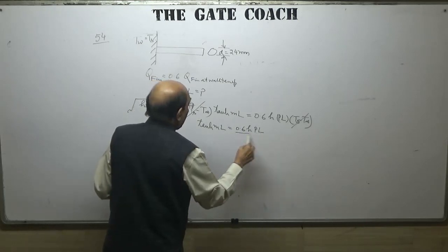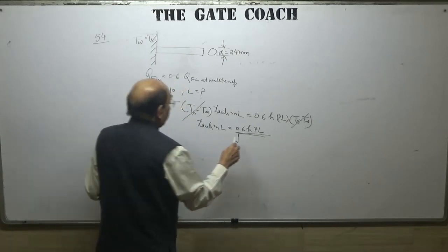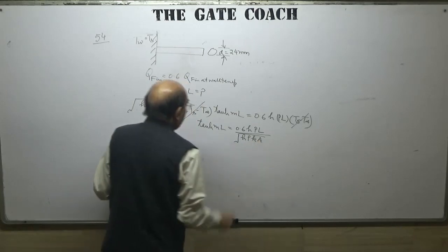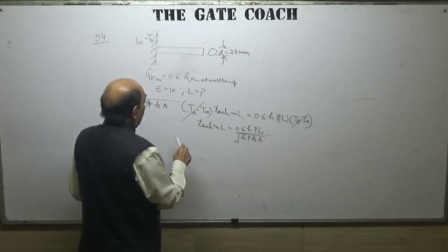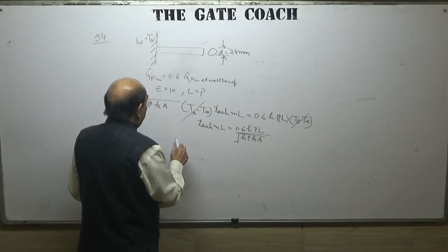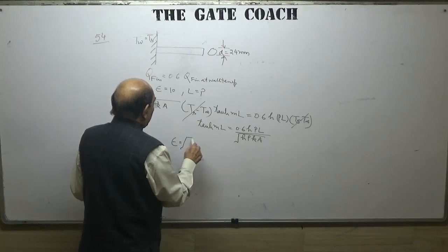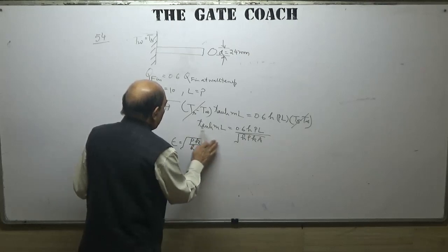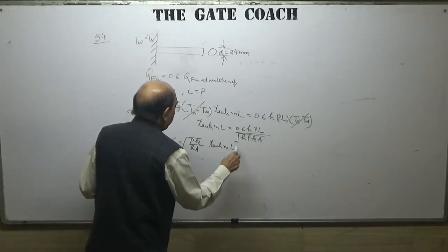The effectiveness of the fin, which if you remember is under root of Pk upon hA into tan hyperbolic mL.